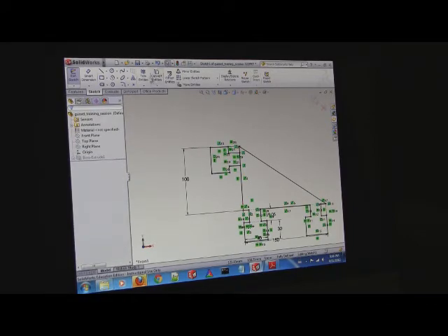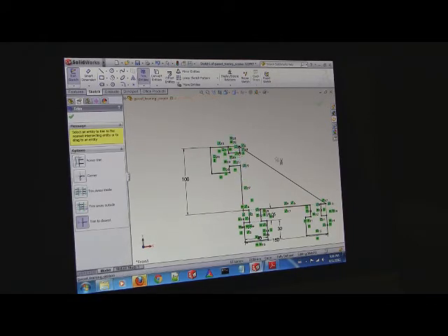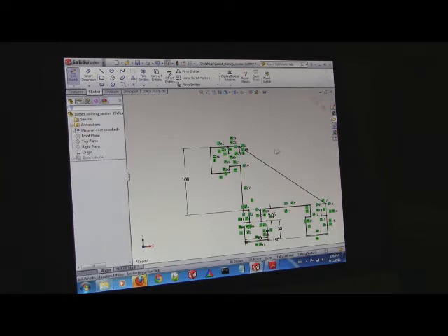And everything should be black, and then trim away that little section that we had. Does it matter the order in which you apply the constraints? Nope, it does not. Did you put them equal to the wedge down here? Yeah. Okay, that's how I got them. It actually doesn't matter. You could set them equal to the other wedge. As long as you never delete any of the wedges, you're fine. You only get into issues if you start referencing things that are referencing things that are referencing other things, because if you delete anything in that chain of references, you're screwed.